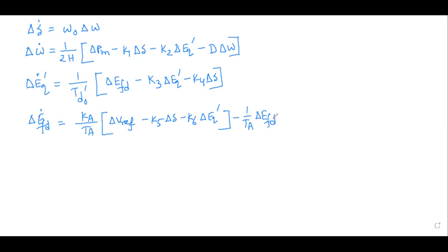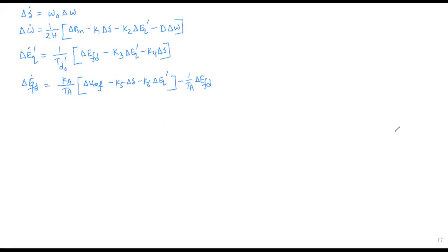Okay, so this is actually the fourth order model that we have got after including the additional state variable generating from the exciter block. So now what would be the corresponding expression for x dot equals Ax plus Bu? Again, we go there. So what is our x? Let's list that. So x transpose would be simply del delta, del omega, del EQ prime, and del EFD.